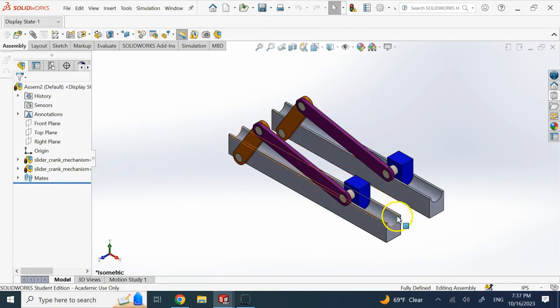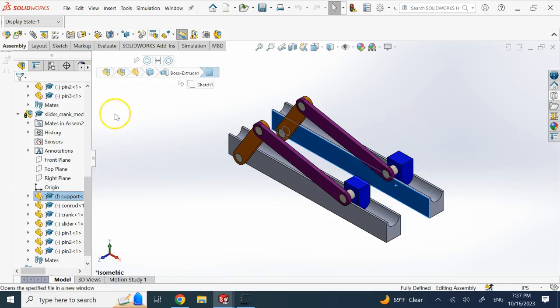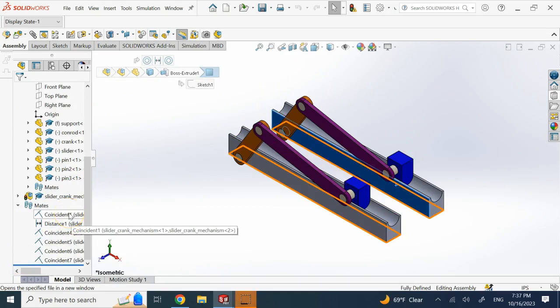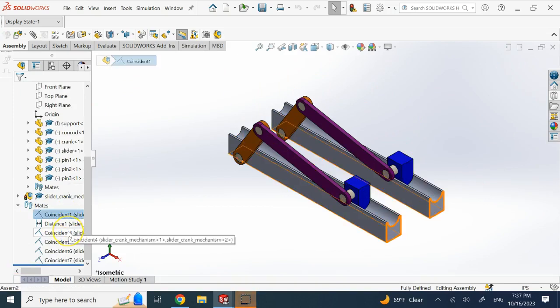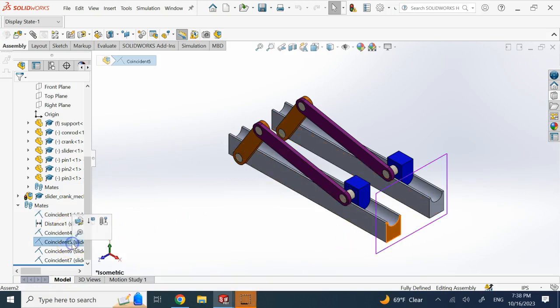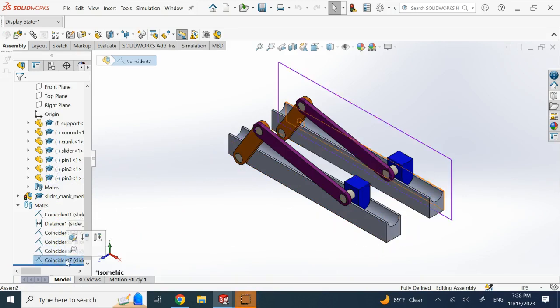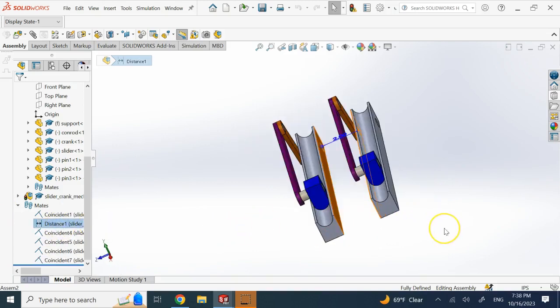So here I positioned these two support blocks, these two base blocks, with respect to my assembly planes. Okay, so I made them coincident with each other, and then coincident with these two also faces coincident, and then using this one, and this one, I place them exactly in a fixed location with respect to what? With respect to the assembly planes. Okay, so you see I made two of the planes of these objects coincident with each other, and then I have a distance between these two planes, 2 inches.